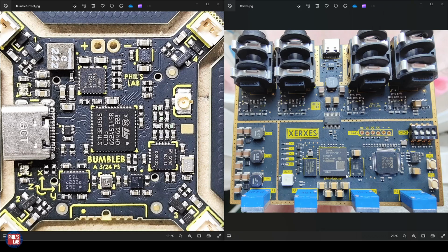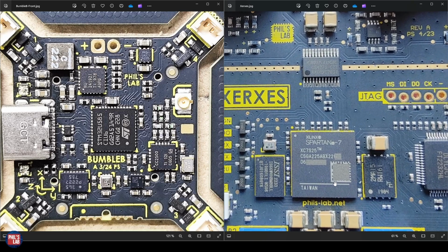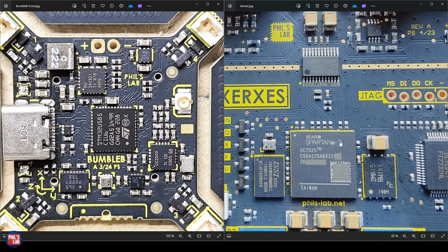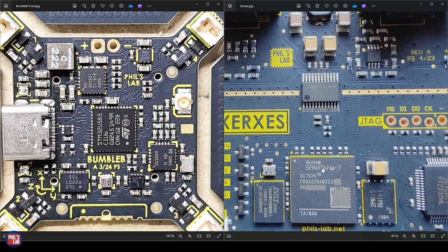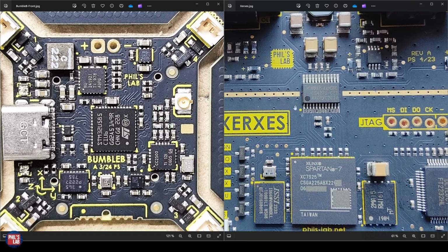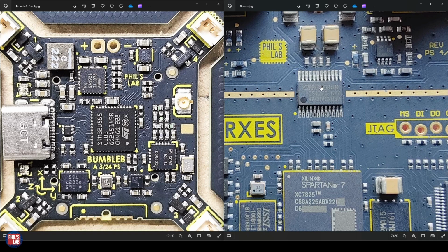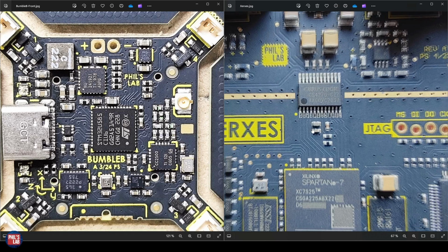Similarly, on the right-hand side, we have similar scenarios where we have one controller, for example, this AMD Xilinx Spartan 7 FPGA, which interfaces via I2S as well as SPI to the Cirrus Logic CS4270 codec. So this contains ADCs and DACs in one single IC. The SPI connection in this case is there to set up the registers internally to the CS4270, for example, to set up sampling rates, bit depths, protocols, and so forth.